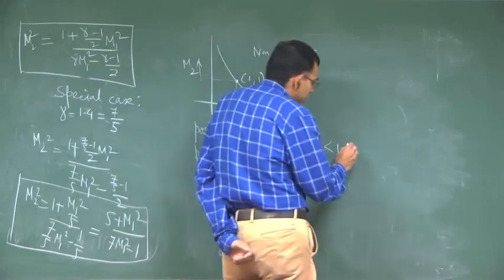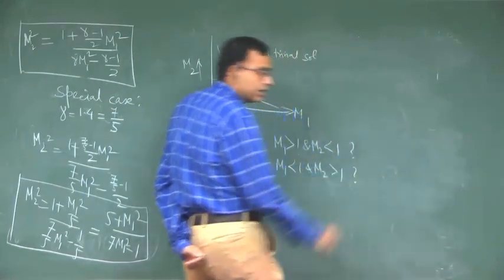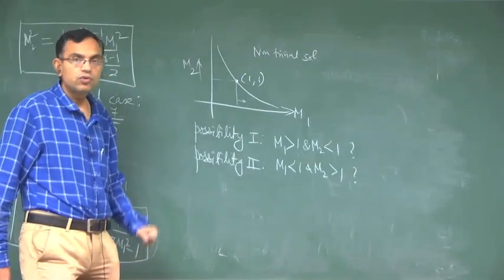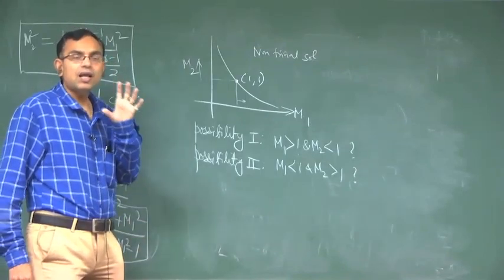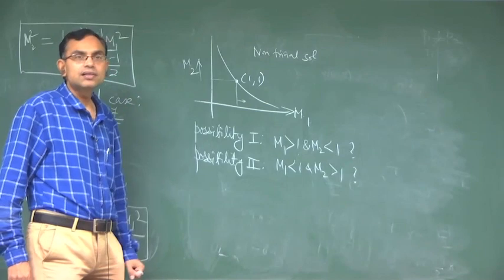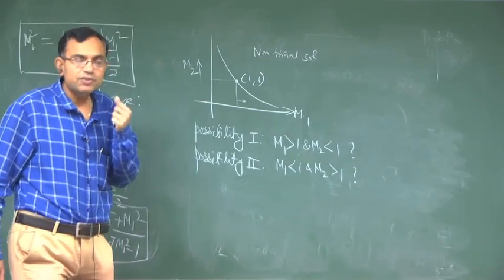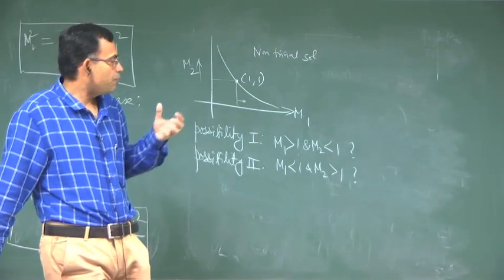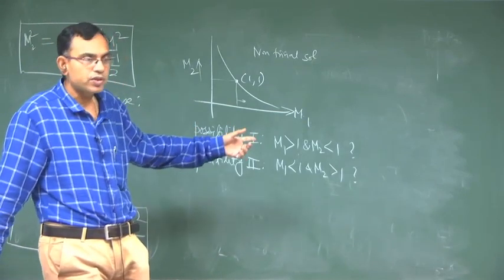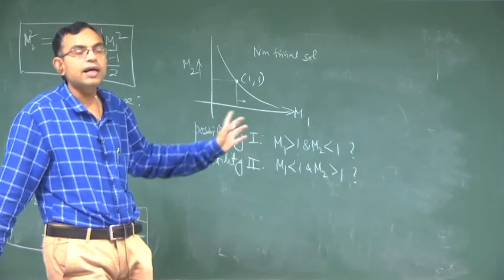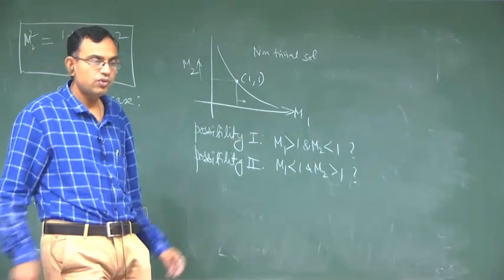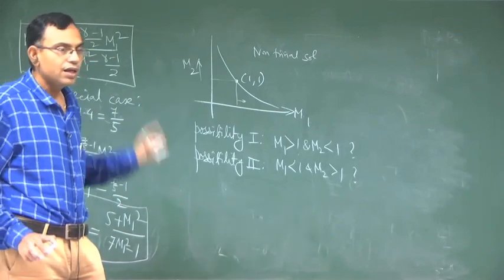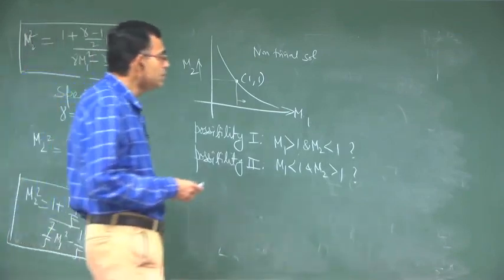The big question that we now raise is, are these possibilities both physically plausible or not? Fluid mechanics alone cannot give an answer to this. Even the first law of thermodynamics, which is the energy balance, cannot give an answer to this. The proper directionality of this process will be governed by the second law of thermodynamics. So, we will now calculate the change in entropy across the shock.